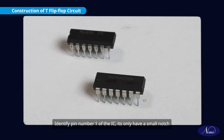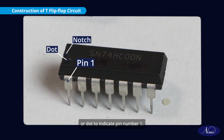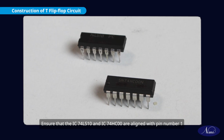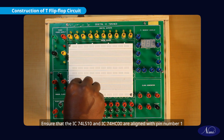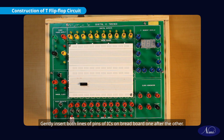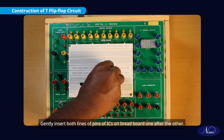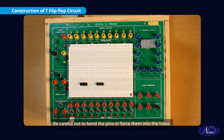Identify pin number 1 of the IC. It only has a small notch or dot to indicate pin number 1. Ensure that the IC74LS10 and IC74HC00 are aligned with pin number 1 correctly over the breadboard in the digital trainer kit. Gently insert both lines of pins of the ICs on the breadboard one after the other. Be careful not to bend the pins or force them into the holes.